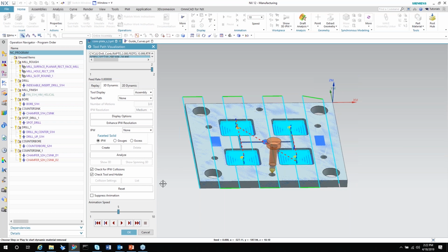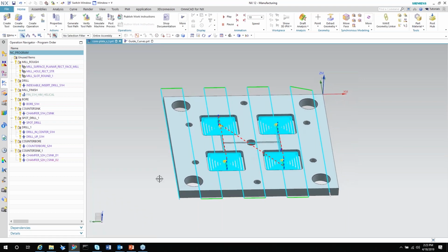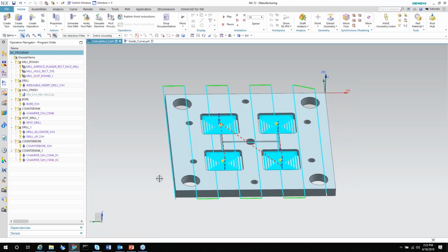They don't have to put tooling in or anything, and they have guaranteed results of 25 to 35% increase, which is great. And it saves the operator time and the tool crib time of setting up those tools and touching them off and loading the carousel for that. So feature-based recognition, feature-based machining, it can be very, very handy.